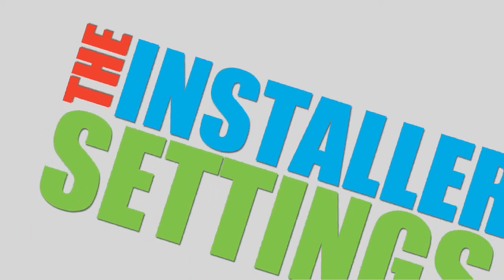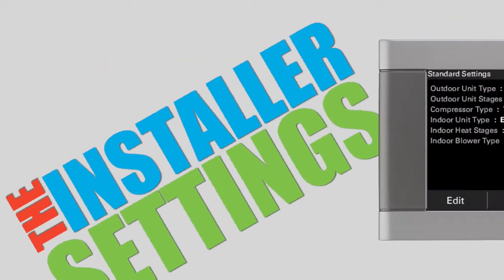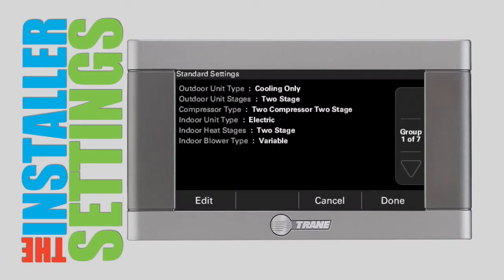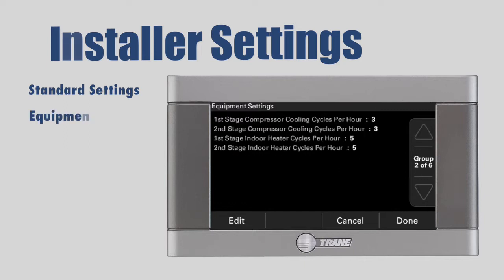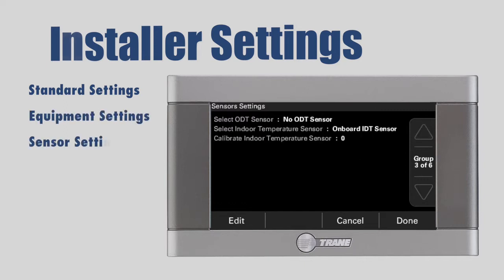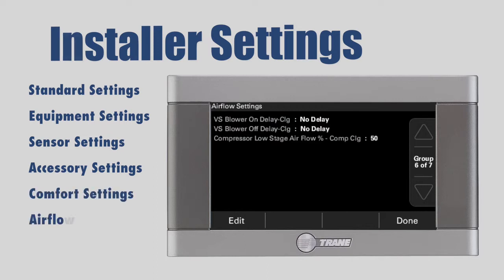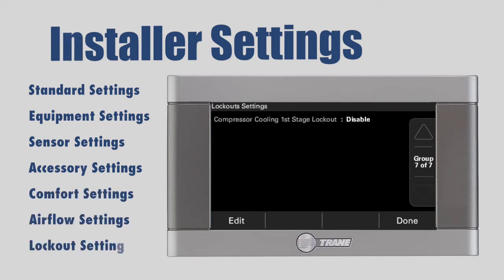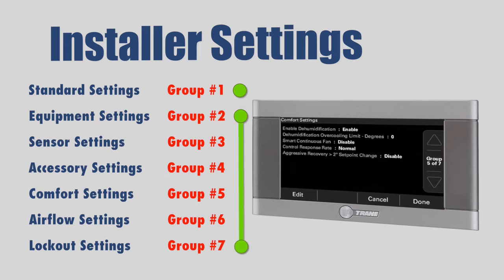Installer Settings. You will now be guided through the Installer Settings section of the Installation Wizard. Installer settings are divided into 7 groups: Standard Settings, Equipment Settings, Sensor Settings, Accessory Settings, Comfort Settings, Airflow Settings, and Lockout Settings. Group 1 indicates what type of equipment is installed, and Groups 2 through 7 allow you to customize a wide range of system settings.